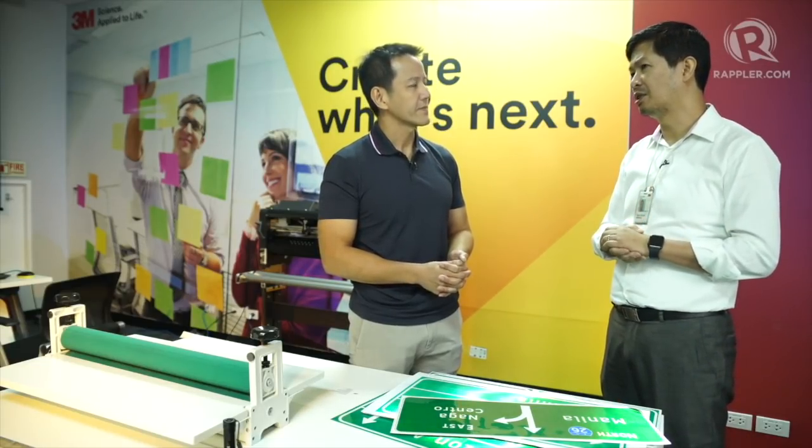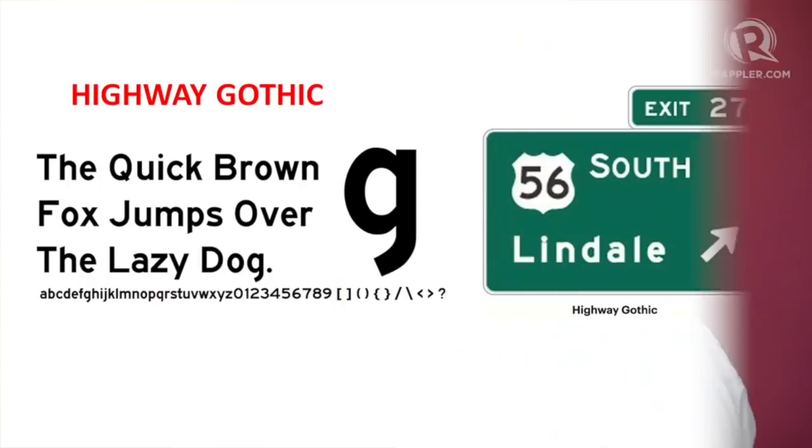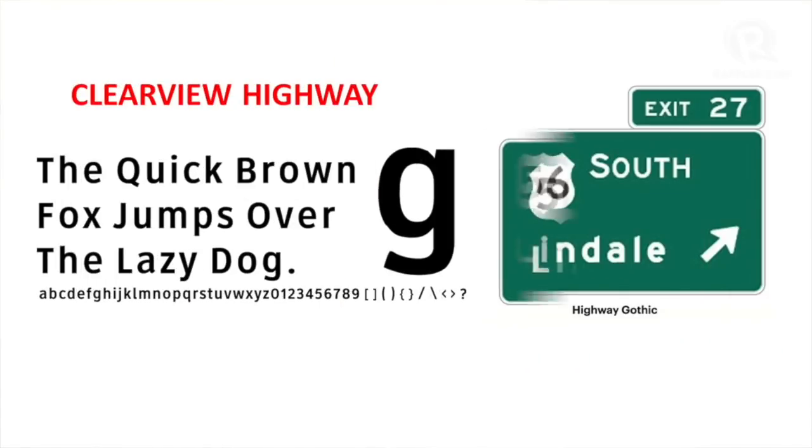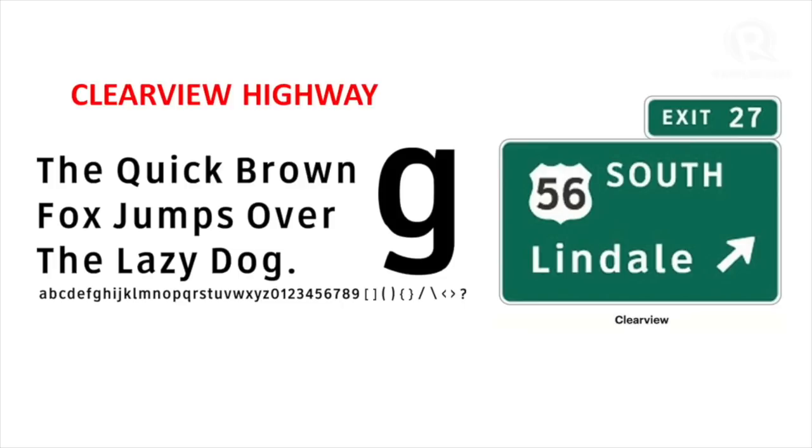I mean, we have to also remember that motorists are moving, depending on the speed zone, could be moving as fast as 100 kilometers per hour. So the font is important because it has to be legible. Yes. So what kind of fonts should we be using on signs? We have two general fonts that we are using, and we have the highway font, highway Gothic fonts, basically. And we have the newer Clearview highway font sizes.